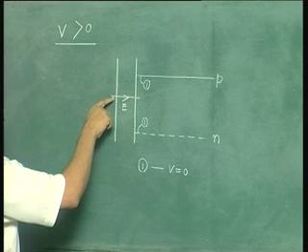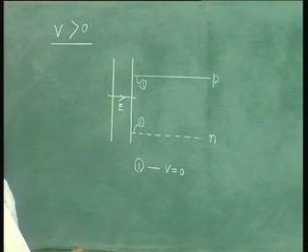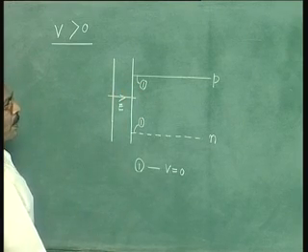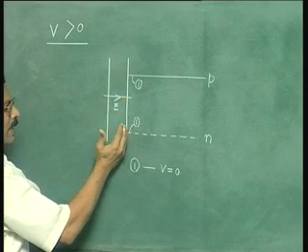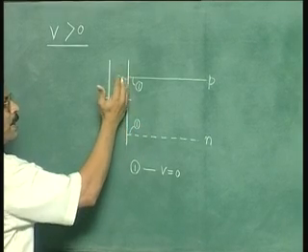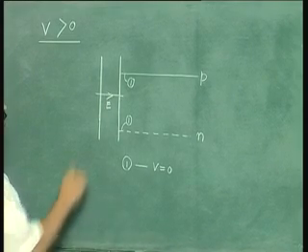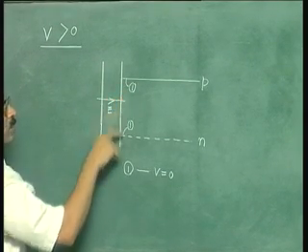Positive charge in the metal is created by removing of electrons. Now how do you create the negative charge in the semiconductor? Clearly negative charge in the semiconductor will be created by attracting electrons or repelling the holes. This electric field will tend to repel the holes and attract the electrons.